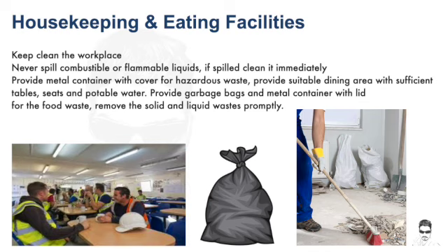Keep clean the workplace. Never spill combustible or flammable liquids. If spilled, clean it immediately. Provide metal container with cover for hazardous waste. Provide suitable dining area with sufficient table, seats and potable water. Provide garbage bags and metal container with lid for the food waste. Remove the solid and liquid waste promptly.